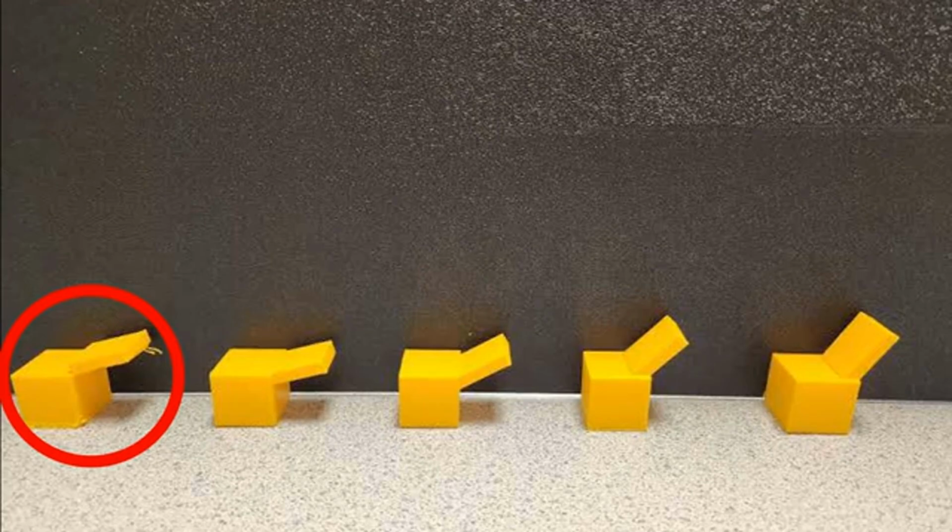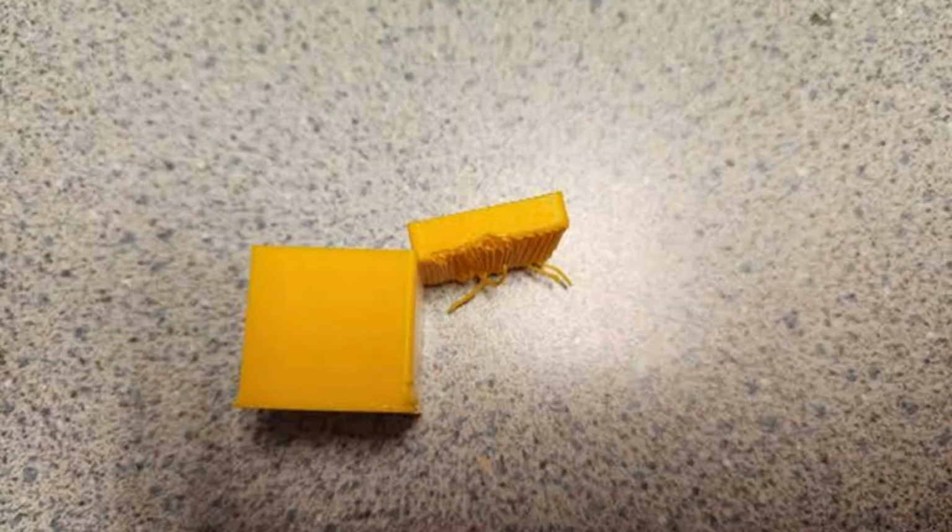Let me show you what it looks like on the underside. If you see it, it was able to print it, but the printer wasn't able to do a great job on it. So it looks a bit messy on the bottom. So I wouldn't recommend doing an angle that's quite that small. You're going to want to make it just a little bit more tilted up.